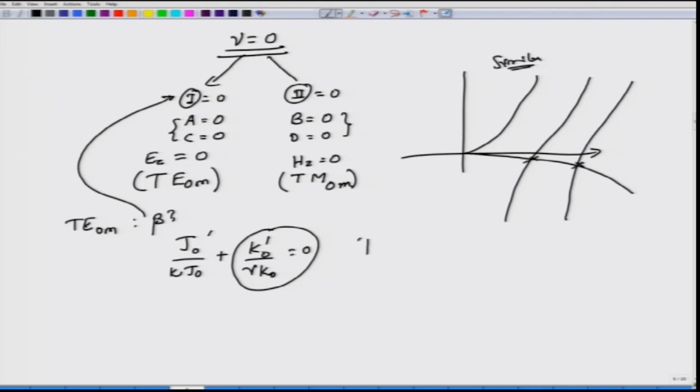So, for the same TE first order 0, you will have multiple modes M, starting with M equals 1, 2, 3 and so on, and correspondingly you will have beta for the TE 0M mode. So, what are the field components for the TE mode? Well, for the transverse electric mode it is Hz, which must of course be some constant B which you do not know, but anyway. So, the fundamental Hz field should be J0 kappa r.